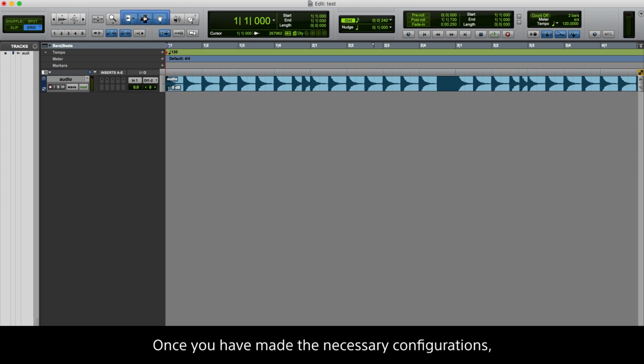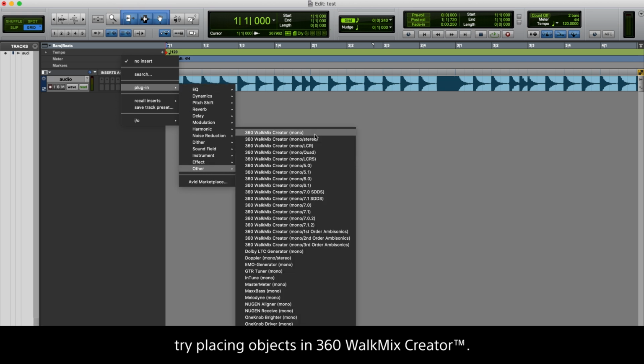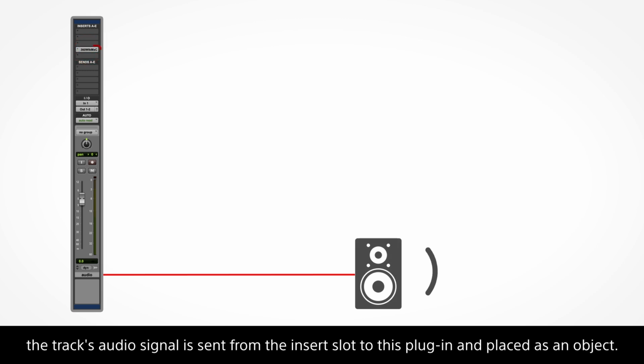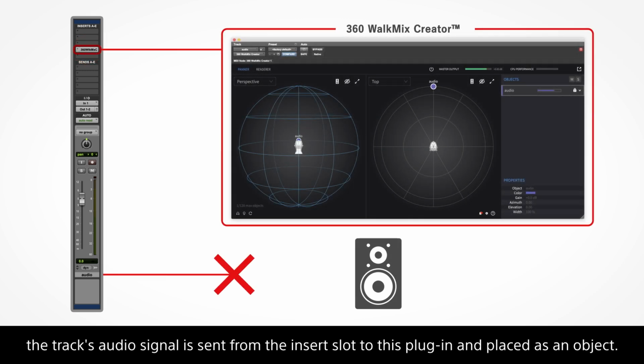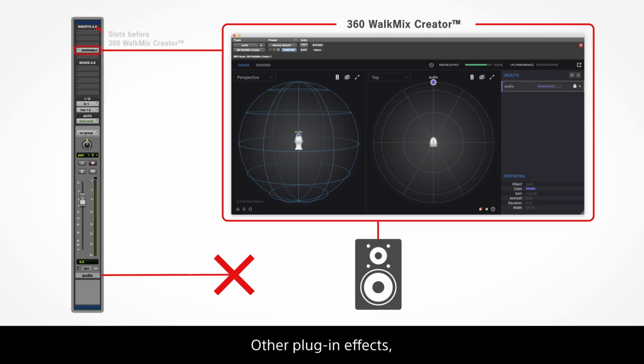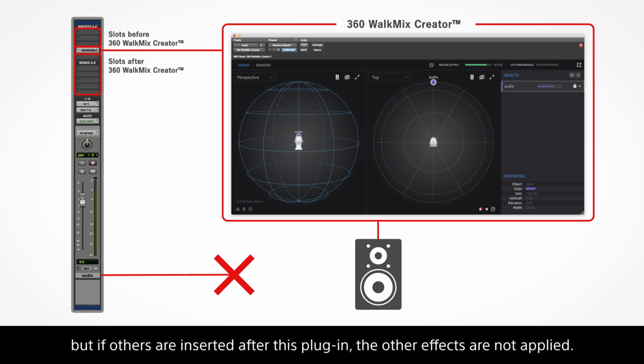Once you have made the necessary configurations, try placing objects in 360 WalkMix Creator. By inserting this plugin into the host DAW's track, the track's audio signal is sent from the insert slot to this plugin and placed as an object. Other plugin effects inserted in slots before this plugin in any tracks are reflected in the object. But if others are inserted after this plugin, the other effects are not applied.